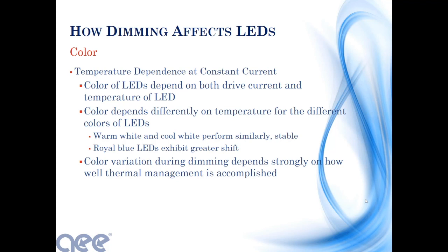But now the real interesting part for me was that depending on the color of the LED itself, now we are typically talking about white light, right? White light LEDs, which are still really blue LEDs, tend to be a little bit more stable. The phosphor over top of it keeps it a little more stable. But if you're looking at static color LEDs, red, blue actually shifts a whole lot more based on temperature than white LEDs.